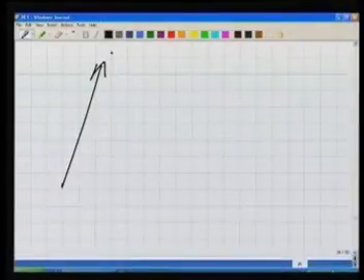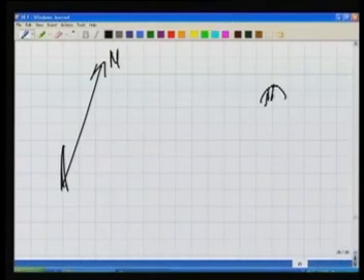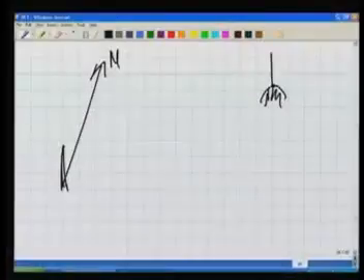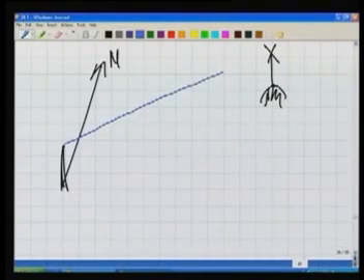So now what can be achieved? If we have a total station, let us say this is northing, or the direction of north, your total station is kept here, and there is a point on the ground, and you want to determine the coordinates of this point. So you have a target kept here. Target means something the total station will bisect. Now the EDMI in the instrument will fire electromagnetic radiation, and once you are bisecting the target, it will be reflected from there. It goes there, gets reflected, and this distance, which is called the sloping distance, is measured.